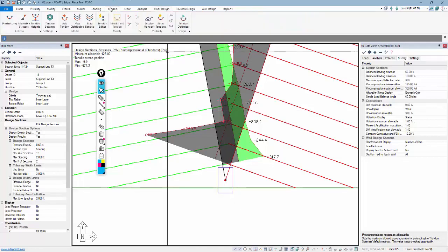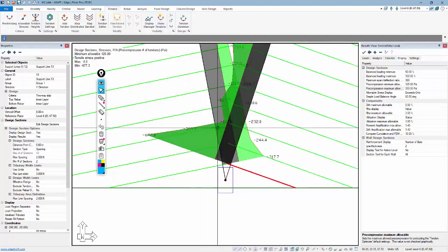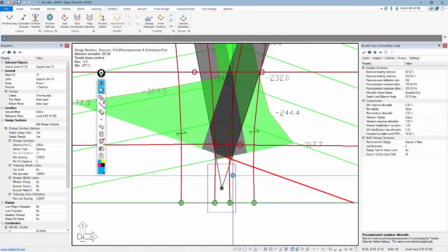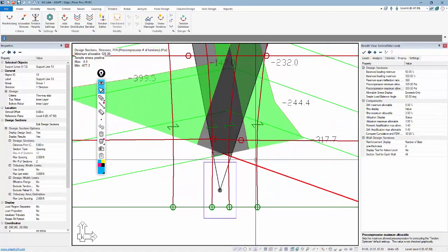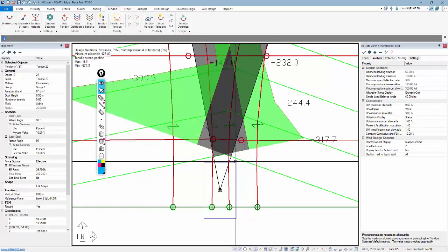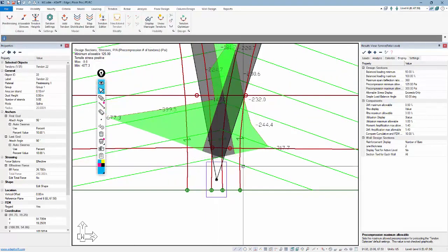And then we have, okay, so that we have tendons that come through here. Let me turn the tendons on. And we have a lot of tendons kind of passing through this joint. So this is really a function of how the strips are set up and how many tendons are kind of converging in this area. And if we look at this cut, we have 2 sets of tendons times 9 times 2. So there's 18 strands intersecting that cut.